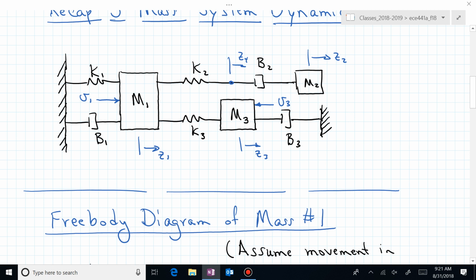You now need the expression that involves the length, the expansion or contraction of that spring to give you a positive force to the left as you've now defined it in terms of Z sub 1 and Z sub 3. And I like to maybe just fix one and let the other one vary, fix the other one, let the other one vary, and see if I have my signs right.